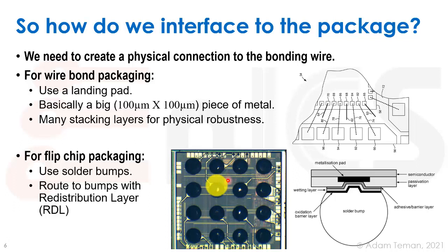What is usually used is something we call a redistribution layer, an RDL, and it's an aluminum type of layer on top of the regular copper layers, which is only used for routing to these bumps. So as you see in this small chip, we have 4x4 bumps, or pad openings I would call them, on top of the chip, and we have this aluminum routing layer, which takes them to whatever IO they should have been connected to, or it can connect straight down to the power grid.